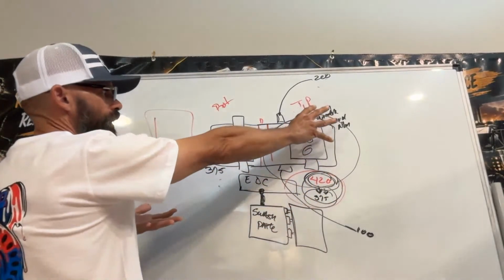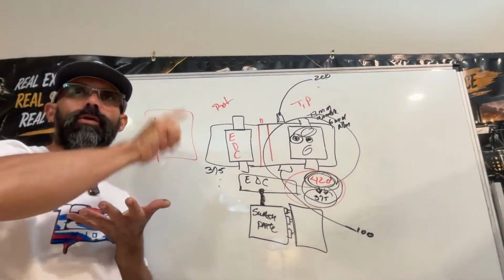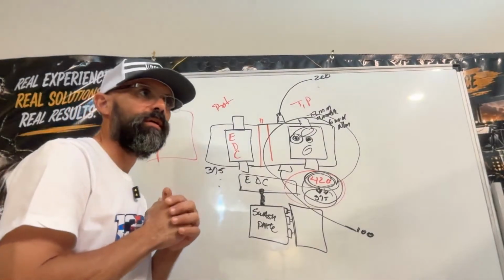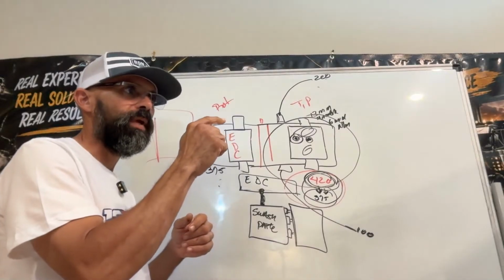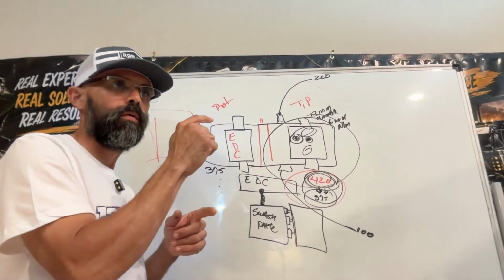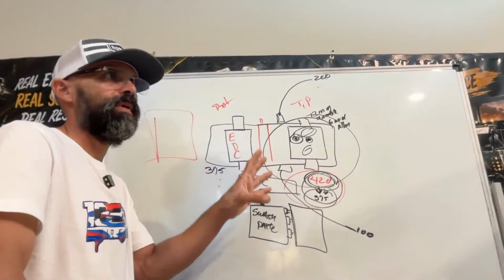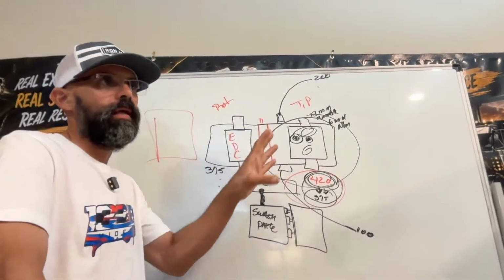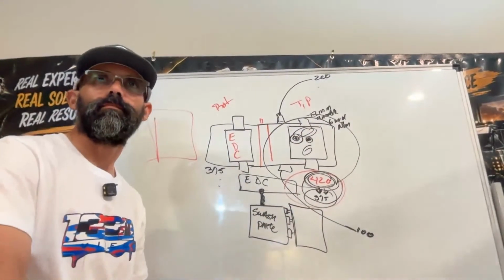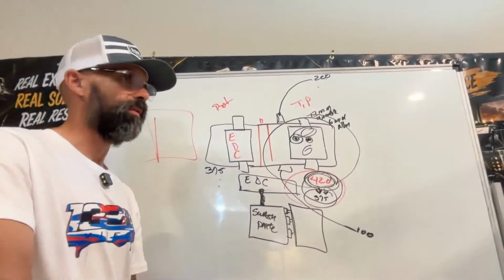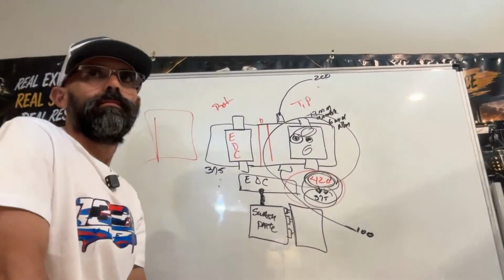So on a thrust and pullback, once you start the machine and you enable it, you're gonna see the carriage maybe creeping forward, or the rotation spinning either clockwise or counterclockwise slowly. All you gotta do on Ditch Witch, American Auger, Vermeer, Toro, Astec, on any system that uses a setup like this, center the pump. That's it. Doesn't mean that the pump is bad. Doesn't mean that there's anything wrong. Maybe just a simple adjustment.